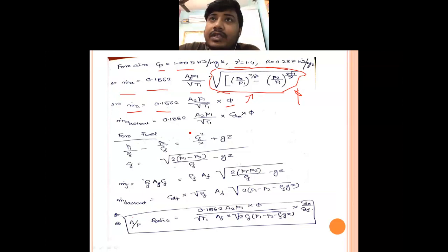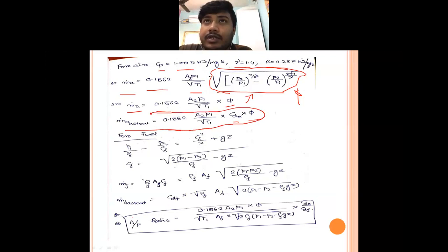So look at over there, the coefficient of discharge value is provided, that is cda. CDA means the coefficient of discharge for air. Okay, so we have got the actual air flow rate in terms of mass like this. So this is a very important equation.